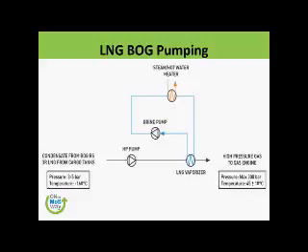This is the element. So reliquefaction is a good idea, but again, for reliquefaction, there is a carbon footprint. You are consuming energy to reliquefy it, isn't it? And bringing something which is in a vapor state or in a gas state, removing so much latent heat from it and changing its state back to liquid, it is an amount of energy.